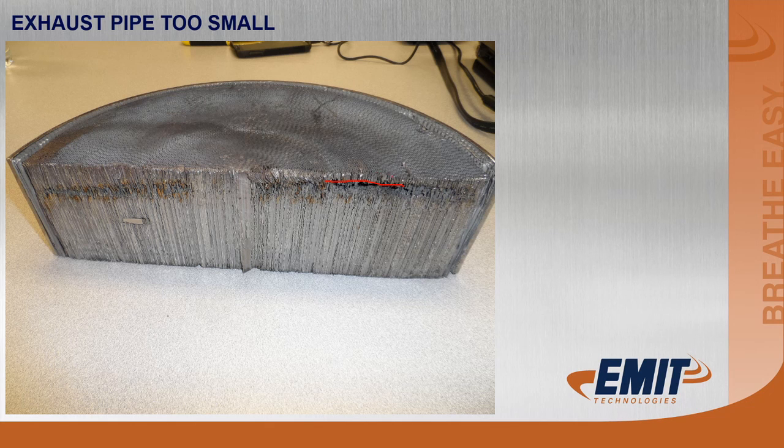And it's just due to a poor running engine or a poor breathing engine, and all the unburned hydrocarbons building up, oxidizing, and had we continued to let this run, this would continue to burn out and get deeper and deeper. But this side of the catalyst would remain just fine because of the low temperatures keeping it cool. So the other thing that this really shows us really well is what part of the catalyst is doing the work. When you're looking at an NSCR catalyst or a catalyst for a rich burn or a three-way catalyst, the activity takes place shortly after it enters the catalyst foil.